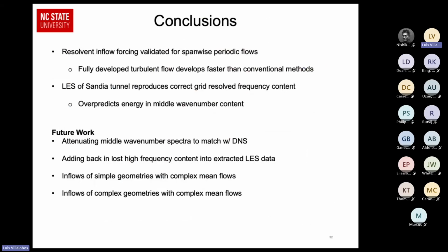Cool. So let's go over conclusions. We showed that we are able to use resolvent inflow forcing for span-wise periodic flows, like a boundary layer or for an axisymmetric nozzle. And we showed that we actually develop a fully turbulent flow faster than conventional methods, or about on par with things like recycling and rescaling.